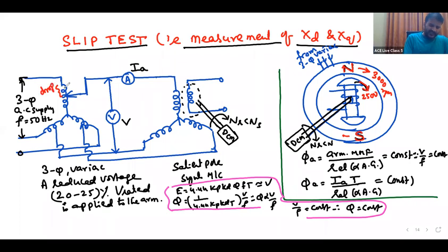We are not changing the voltage; the drop depends on the current. Here we are drawing minimum current, so the drop in the variac is minimum. When the drop is minimum, the output voltage is maximum. Voltage is more. I hope you understood.